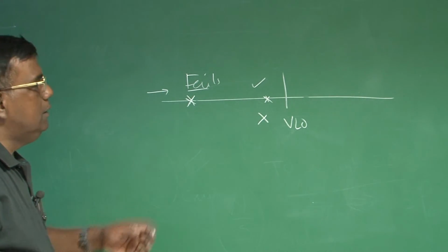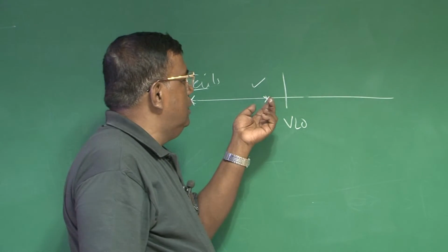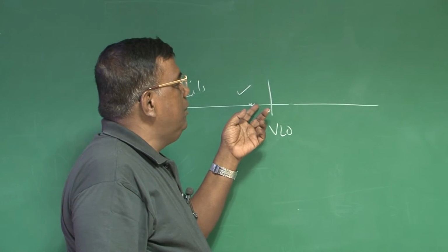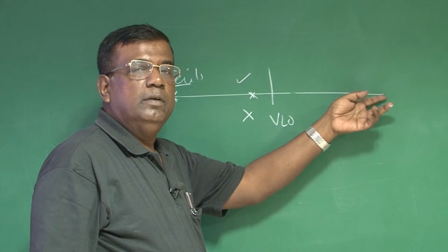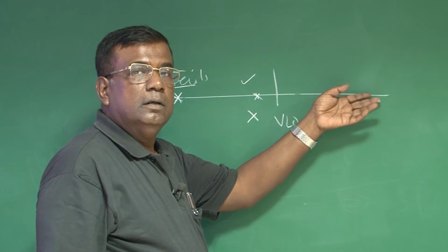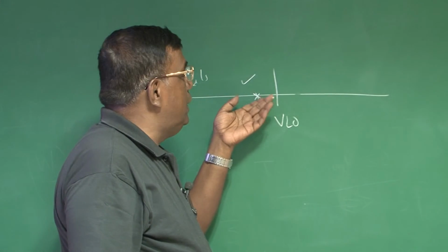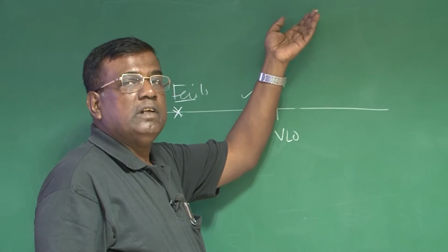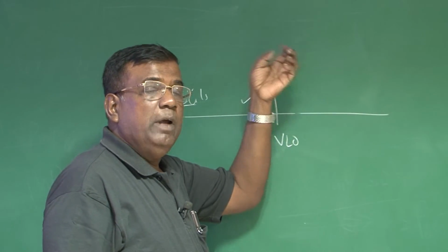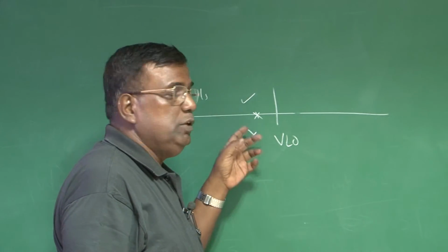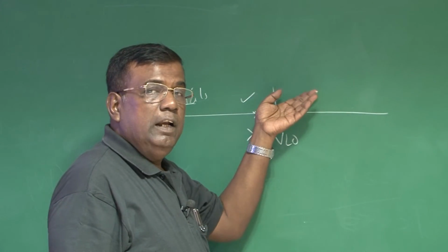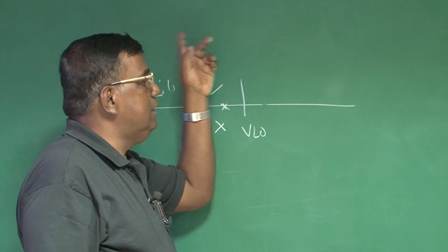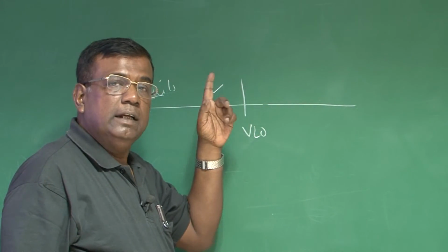Now the question is, if it fails very close to V liftoff, it is possible that I may not have sufficient length available to apply brake. Instead, I should ensure that even after one engine has failed, I should be able to do a prescribed rate of climb that may not be as high as the rate of climb with 2 engines, but fairly good enough, and then go for a circuit and land back, right?